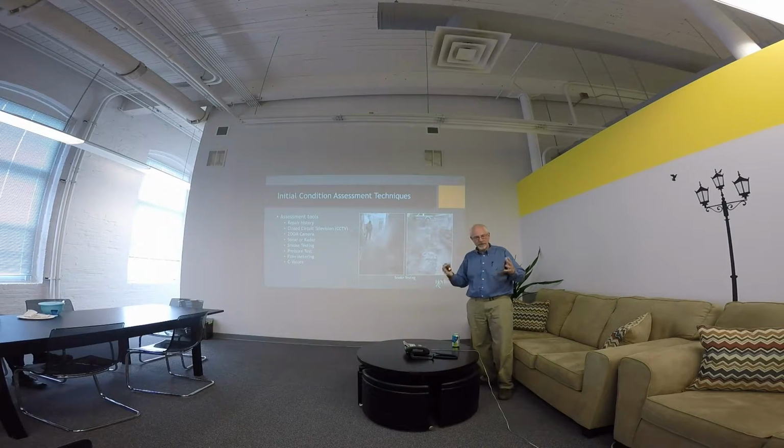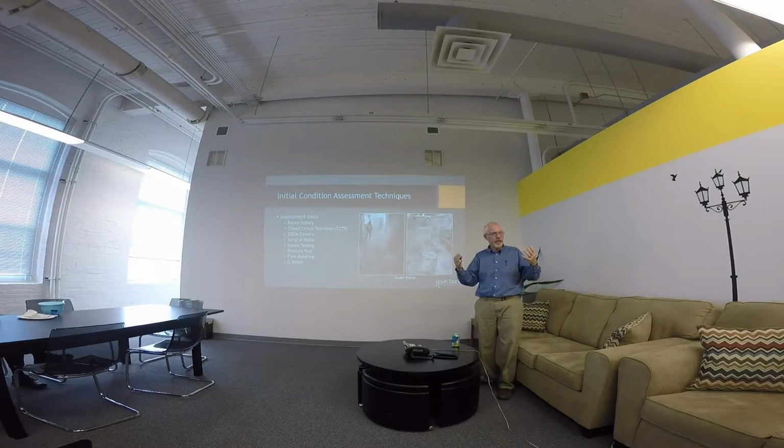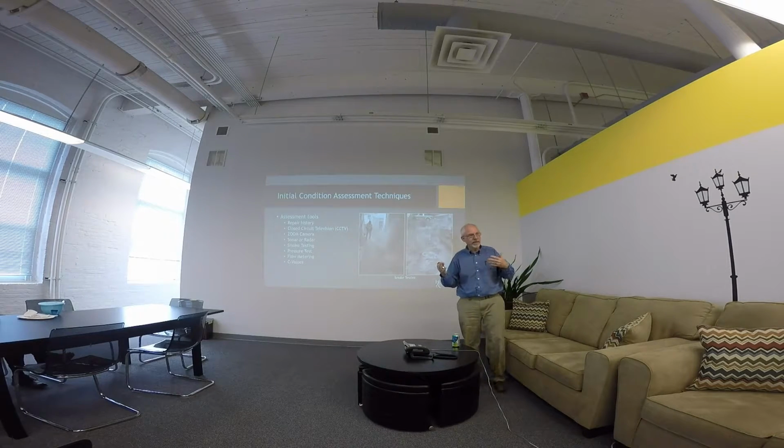They have Logi balls that go down water pipes, and it uses sonar to pick up the thickness of the metal pipe, and will pick up pits and everything else along the way, and they take it out. When you do analysis or condition analysis like that, you have to do a risk benefit because it's not cheap.